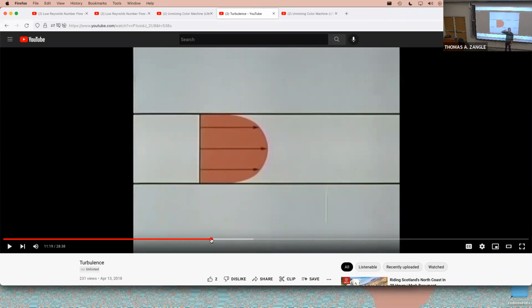That's why there's no vertical velocity shown: if the flow is all the way down the pipe, the only non-zero time average component is U bar, and the V and W time average components are zero.